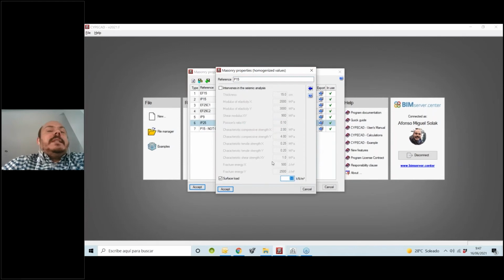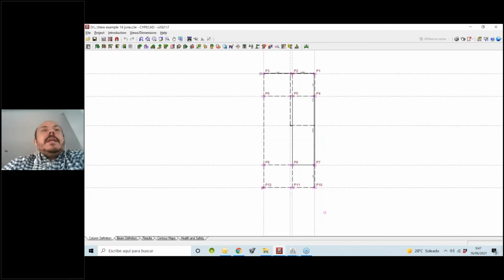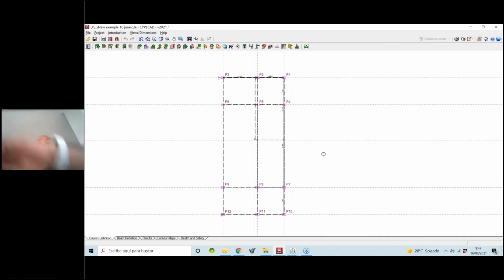We are converting the walls into linear loads. Actually, here we define a surface load, then the software will calculate it, considering the area of these walls, to generate the linear loads. Okay, and if we accept, you can see here that the model was introduced.